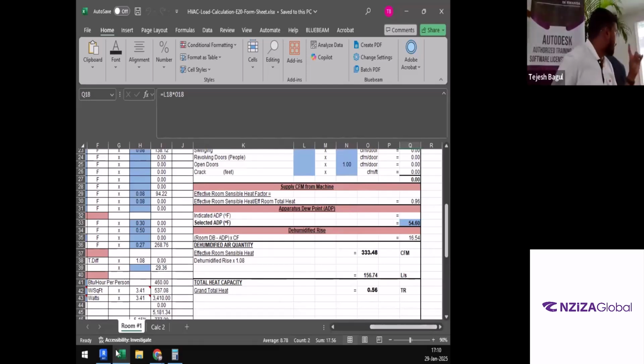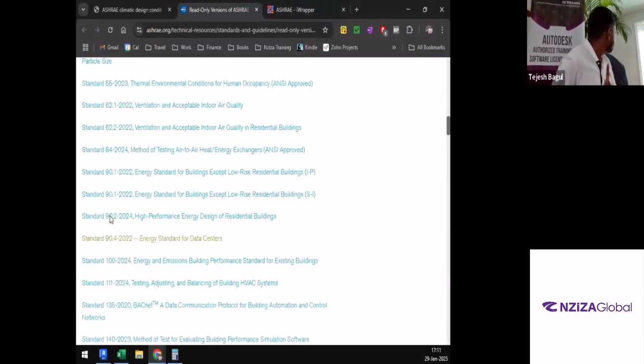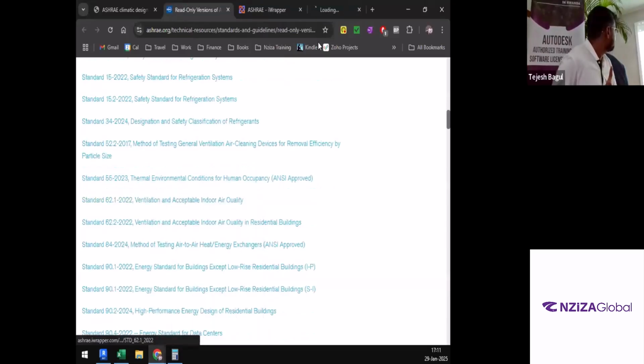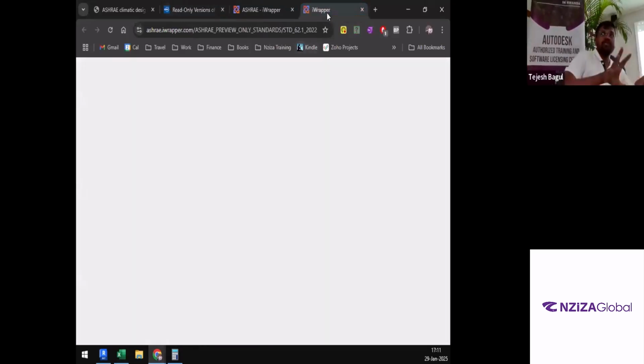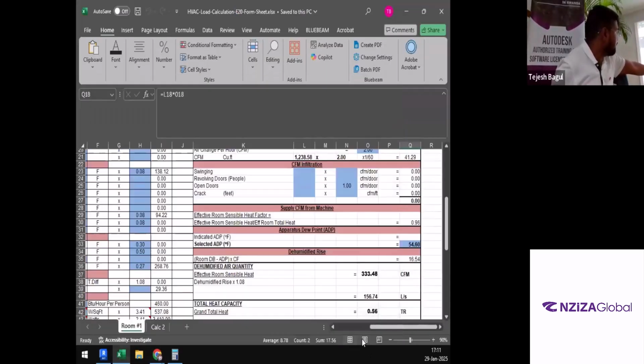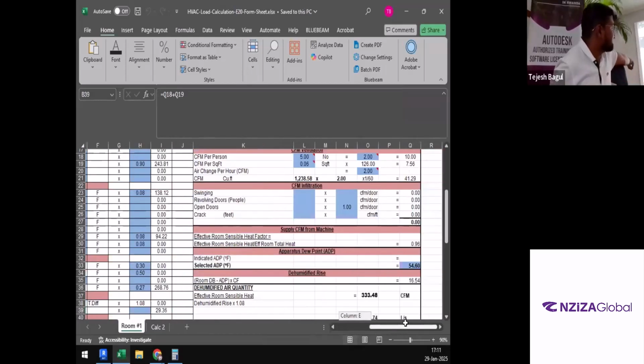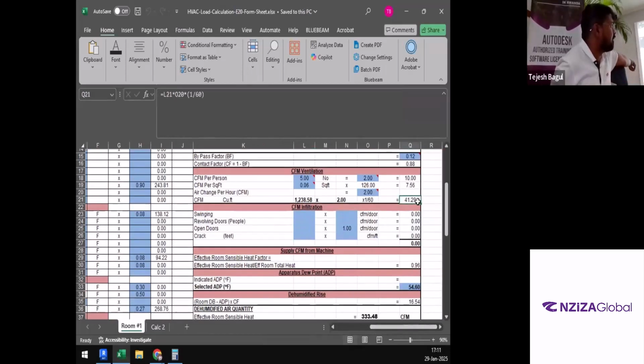Okay. So now that is specifically focused towards occupancies except the hospitals. In here you will get information, I'll open that in a minute. But this 17.6 that we are getting is from that point. So this 17.6, in addition to the 41.29 CFM that we got from ASHRAE 170, is what we will be using to calculate our total outside air load.